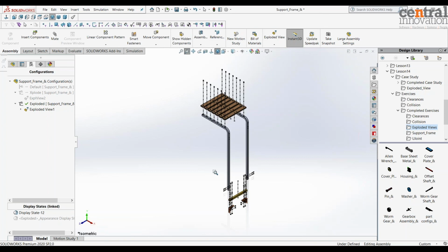So I finished with the exploded view, and within these three case studies, you could see how easy and quick it could be to create your exploded view. But beforehand, if you can plan what you want from the exploded view, especially if you want an animation, you can think of your orders. However, you always have the chance to go back and edit your step, reorder them, or add some component to your steps in the exploded view.